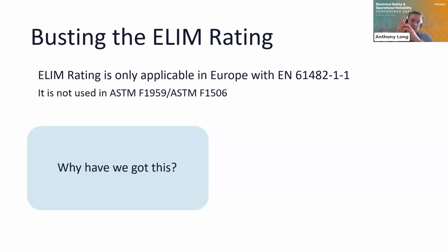So when we look at the possibilities or probabilities of burn, it's a really clear indication that there's no real probability. It either burns or it doesn't. If it burns or breaks open, it failed. If it doesn't, it gets the class 1 or class 2 rating, whatever it is. It might be a fantastic fabric that easily achieves class 1. It goes for a class 2 arc test, it breaks open or burns, and then it's a write-off, even though it might be only a very slim way away from class 2. There's no middle ground, and it reverts back to being a class 1 article.